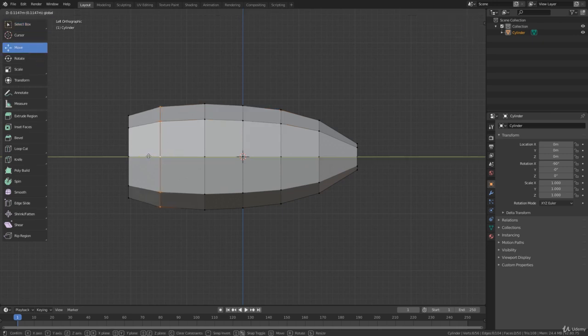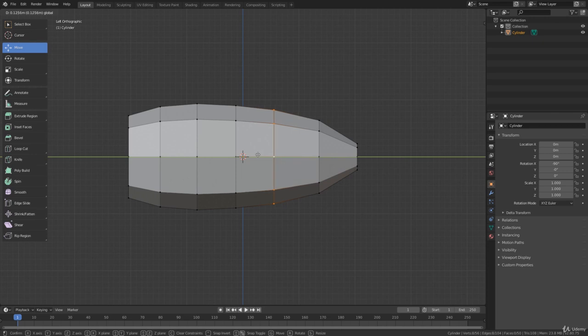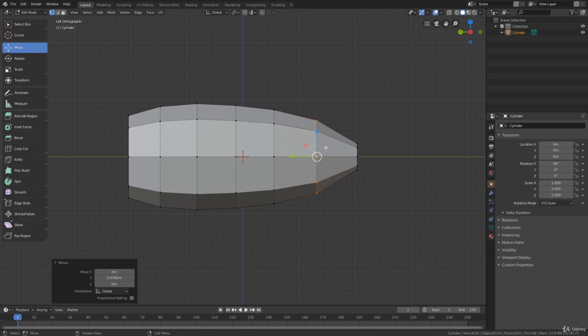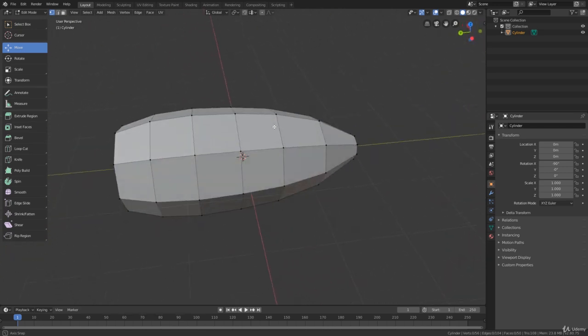and so that the cabin is created more to the front, I'm going to move all the loops one by one by selecting the loop with the Alt key and move the loop forward in the Y-axis using the Move tool. So just clicking the loop with the Alt key pressed, and with the Move tool, move the loop a bit forward, like this. Maybe now I can press the S key to scale this loop down a bit, always checking if this profile is arced, is round like the reference.